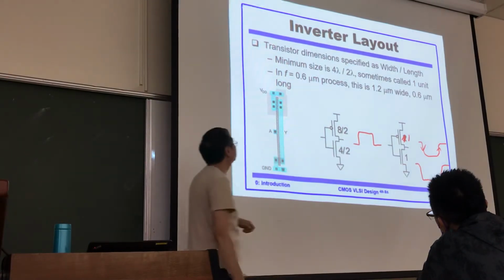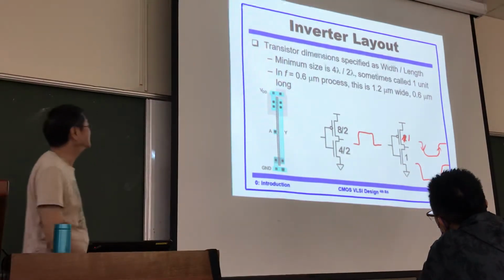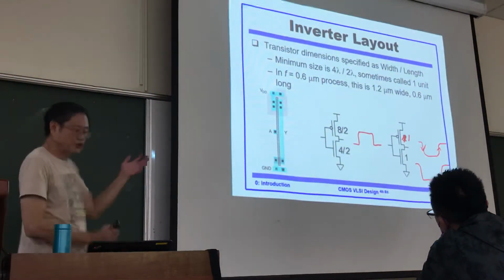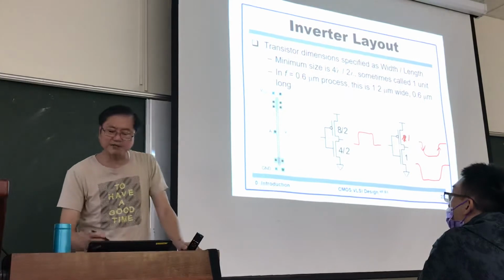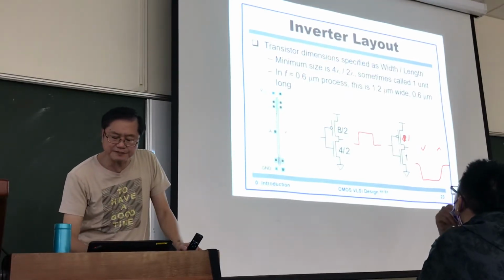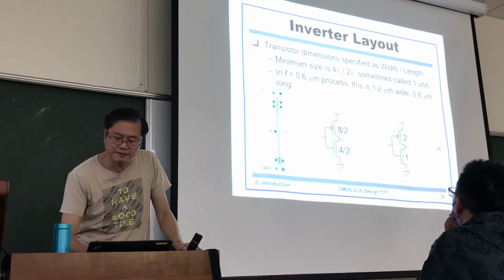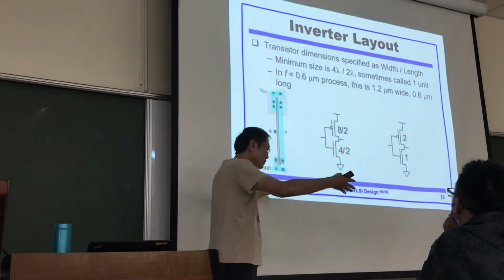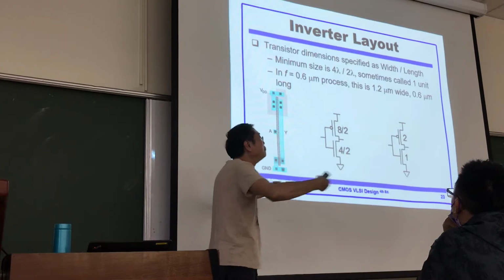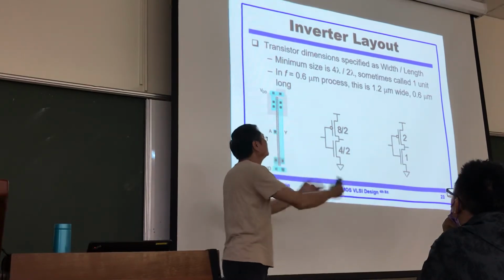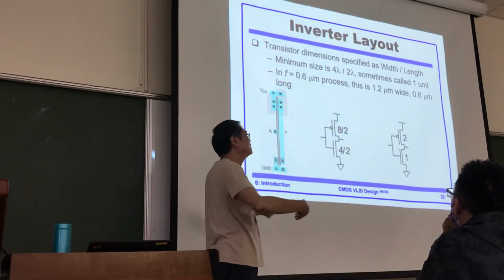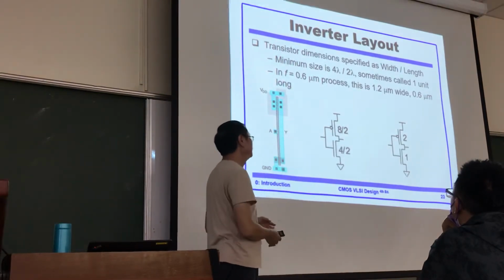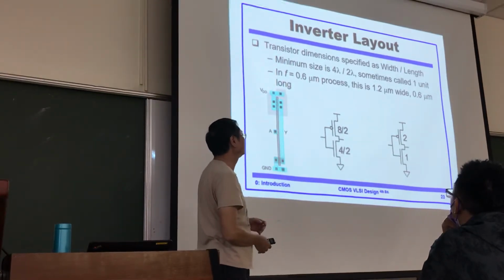Okay, that's the idea behind the circuit. All right. So let me give you another example. How about this? So let's say if you have wider PMOS transistor, then more hole goes through, right? Double the number of the hole goes through the transistor. So that will compensate your circuit speed.